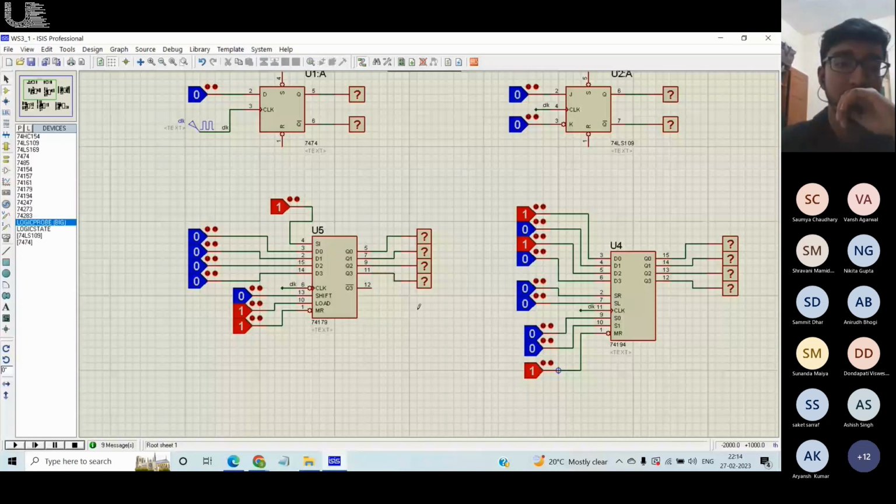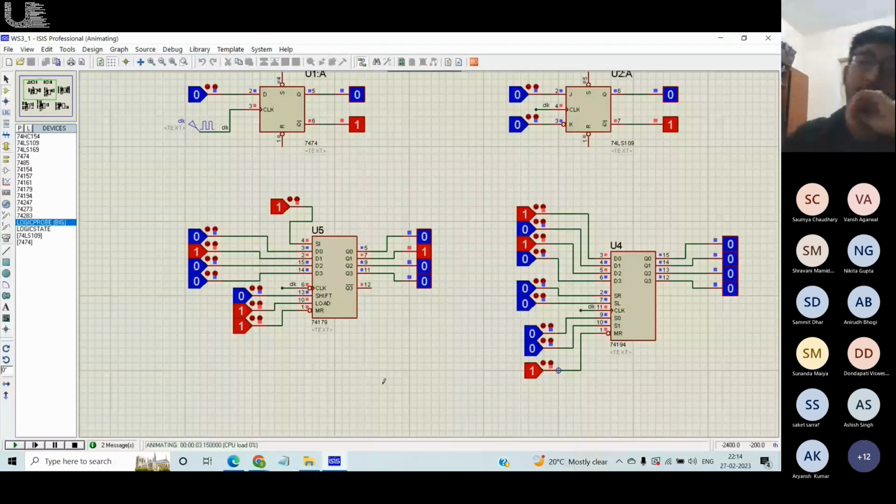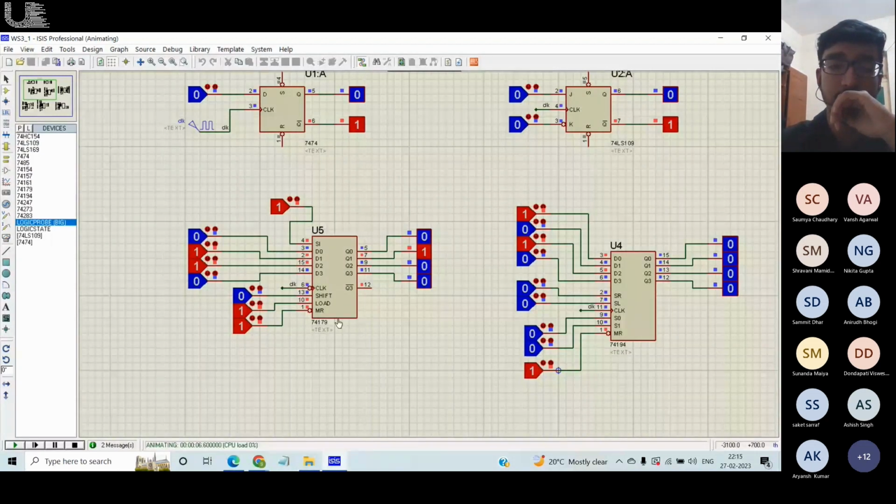If you look at this number, this is 0 in binary. This is 2, if I'm making this the MSB and this the LSB. So you see whatever is here will come there after the first clock cycle. It will stay there because I'm not changing anything. If I change this to 6, then it becomes 6. Now, if I'm not loading but shifting, I'll make shift and load as 0. When both are 0, nothing happens.